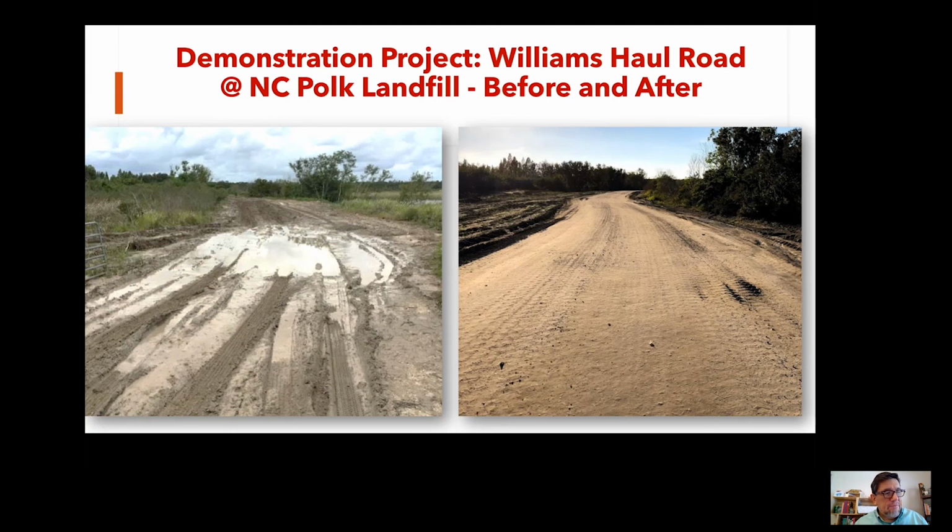Here's an example of a haul road that was stabilized with Consolid. This dirt road is in Lakeland, Florida, and was on formerly mined land consisting of very clayey sand, and it had persistent problems that you see here on the left that made it almost unusable at times during the year. Since stabilization, it's gone through 2 wet seasons without rutting, rilling, or potholing. Now, traffic is not very high on this road, but the loading is. The county uses 20-ton cubic yard dump trucks, and they're running on there every day. The road has performed well since it was stabilized in November of 2018.